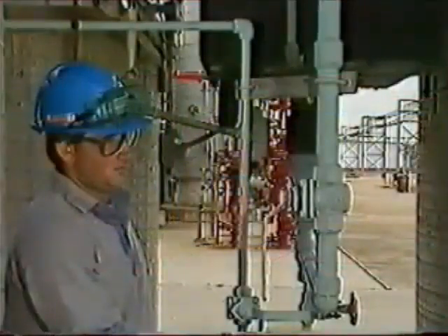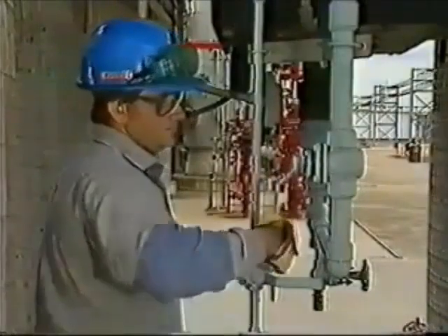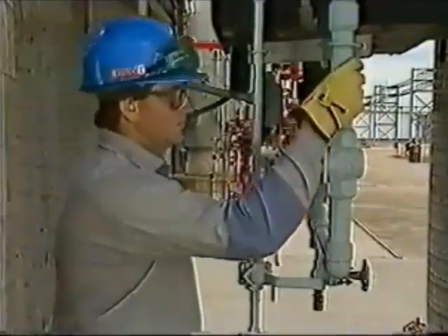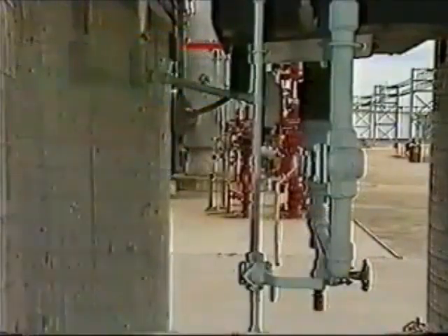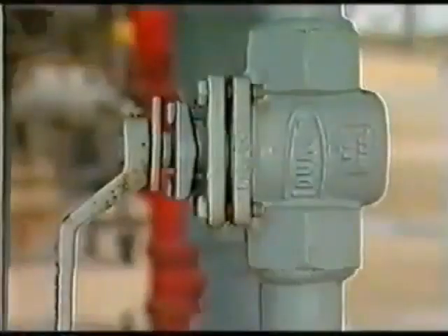The operator can determine if the ball valve is open or closed by looking to see which way the groove at the top of the stem is pointing. When the valve is open, the groove runs parallel to the pipe. Closing the valve rotates the groove across the line of flow. Sometimes, however, the stem breaks away from the ball, so don't bet your life on the position of the stem. Use proper line breaking or blanking procedures and be skeptical around quarter-turn valves whose stems indicate they are closed.